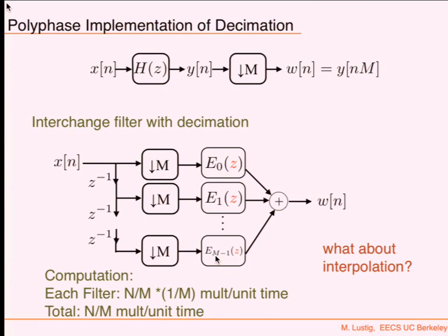Okay, let's say I wanted to do different operations in different bands of frequency. I can do bandpass filters and then do operations and then combine them together, right? I could have done that. But if I did bandpass filters, I might as well downsample, do the operations there at a lower rate, and then go back, instead of filtering on this high rate signal. Okay? So we're going to show you that.